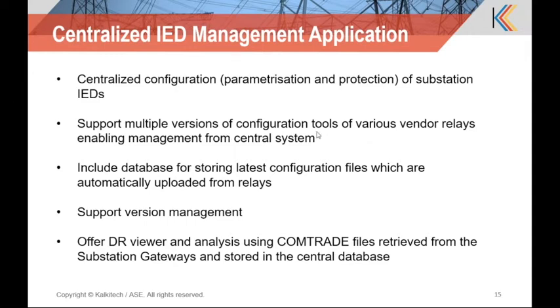So PSCS supports multiple versions of the tool, and it can launch a specific version from a specific location. It has a database for storing the latest configuration file, which can be automatically uploaded from the relays as well. It supports version management. It has a basic DR COMTRADE viewing functionality. If you need a detailed analysis, the corresponding tool can be linked to the DR analyzer and to PSCS, and when you open the corresponding COMTRADE file it is opened in that tool, and analysis and reports can be generated automatically.